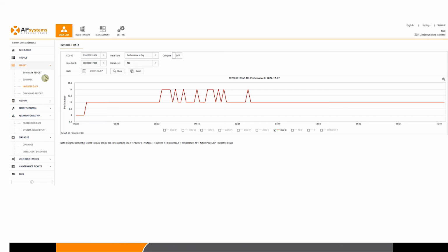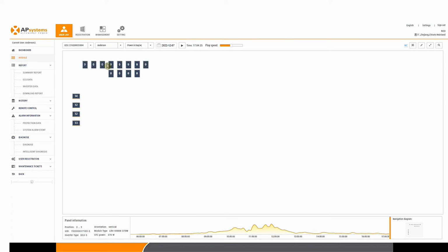And because if the AC voltage is not to a certain limit, like the alarm said, the inverter will not produce power. It will not start up because it's a safety mechanism. So unless this AC voltage hits 230 or 220, whatever the limit is, those panels will not turn on or produce power. So for this one, you can tell the installer that, hey, look, I think that those panels or the trunk line is disconnected.